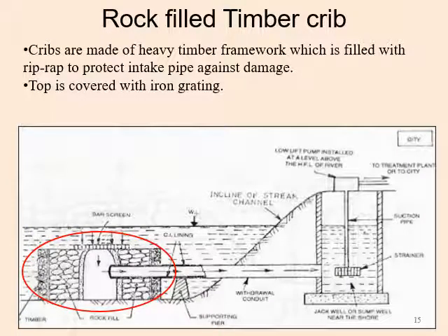So here, the rock-filled timber crib supporting structure is shown. Here in the red circle, it is shown that a bar screen is fitted and the withdrawal conduit is opened on a timber supported rock filled structure.